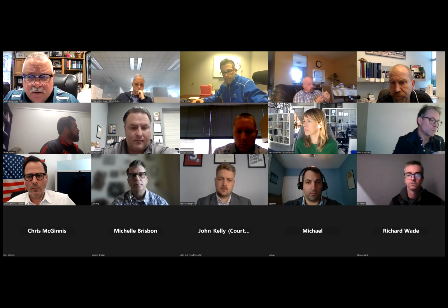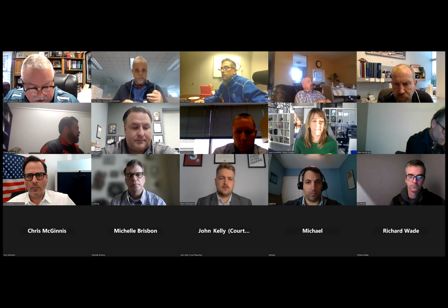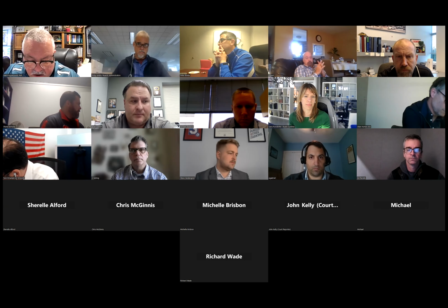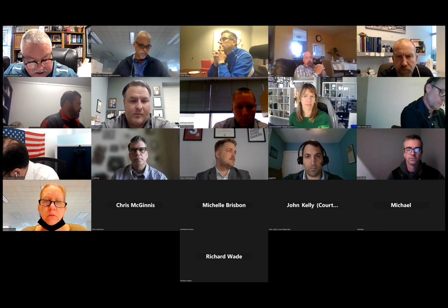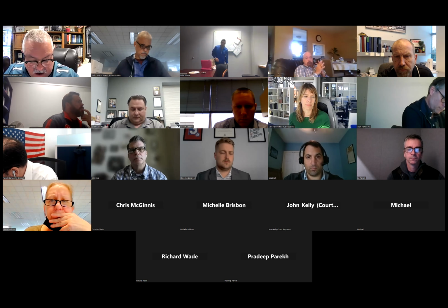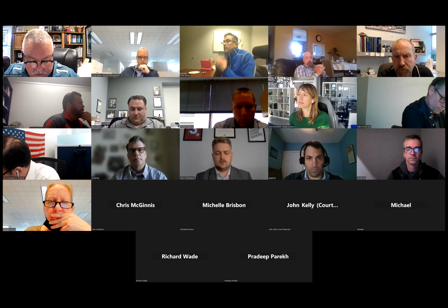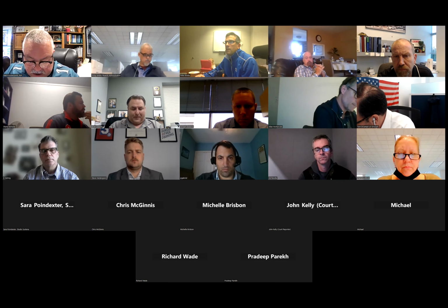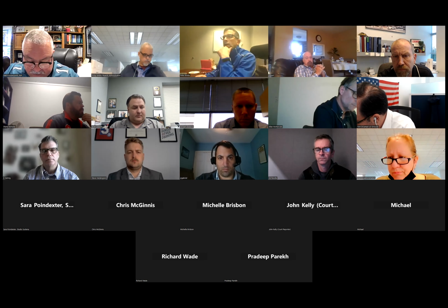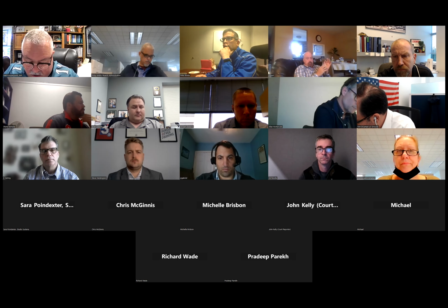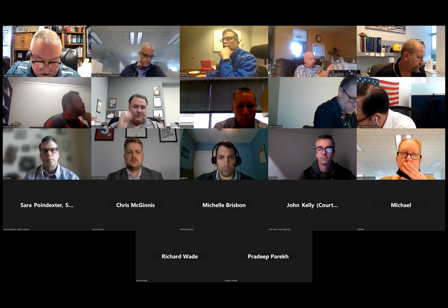Do I have a second on the motion? I second that motion. Thank you. The provisions for approval will be as follows. The first provision is that the sensors for the overflow storm drainage are to be part of the building management system. The second provision, the building management system is to have a backup power source in the event of power failure. The third provision for approval would be there will be no mechanical means of detection on the overflow drainage system. And lastly, the fourth provision is the sizing of the storm lines shown will be resized to utilize 6 inches of rainfall or the old 2004 code, which the building was constructed under.